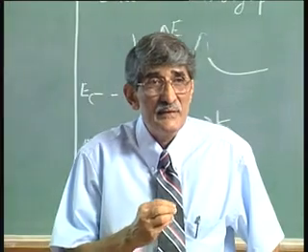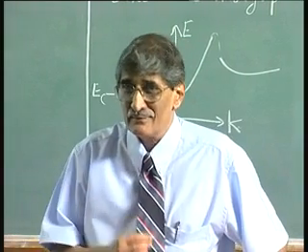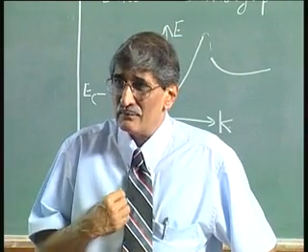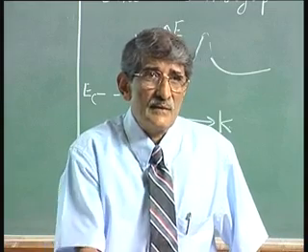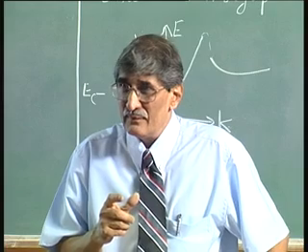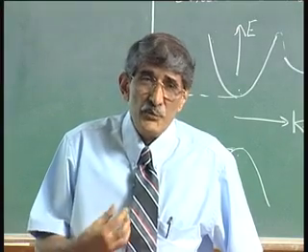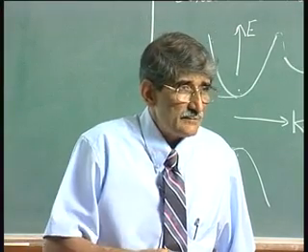The electrons that you get will be from the impurities that you add. These impurities can be intentional or unintentional. You want the devices to depend upon your intentional doping, intentional donors, intentional acceptors. Those are the ones which actually affect this mobility. You get the range of mobility because of unwanted impurities and vacancies which are present, which act as some sort of dopants. So if you get better material, that means purer material, you get better mobility. That is why the range.